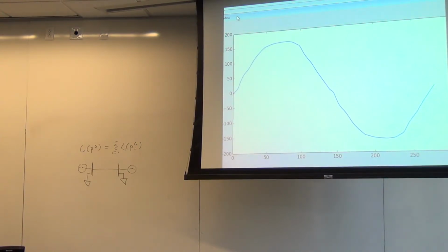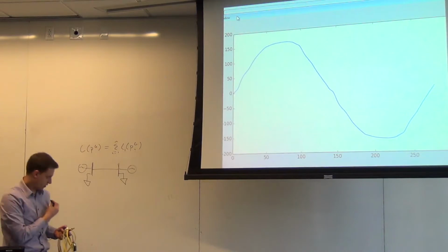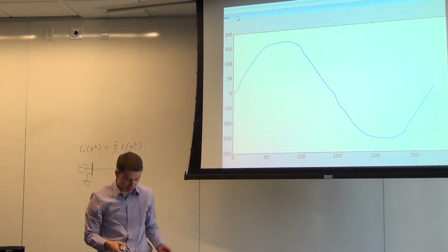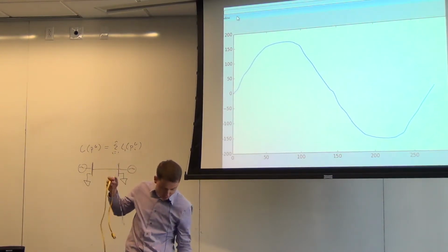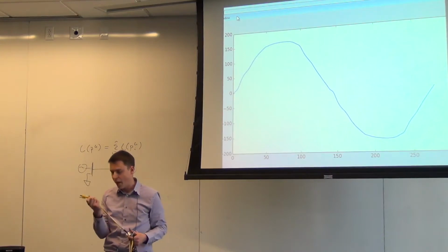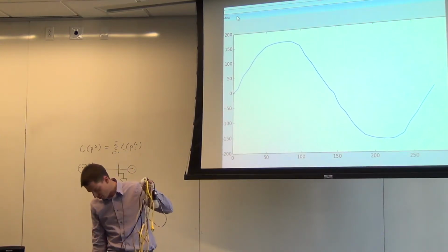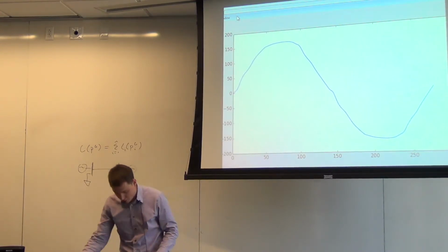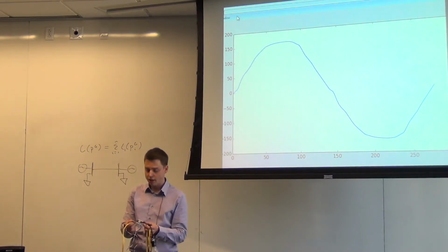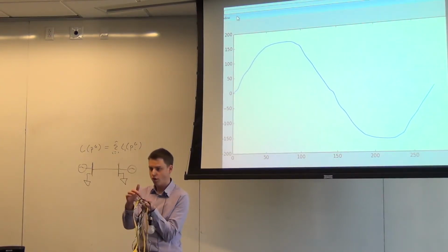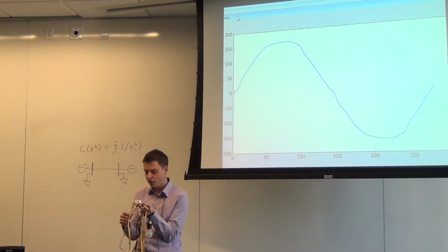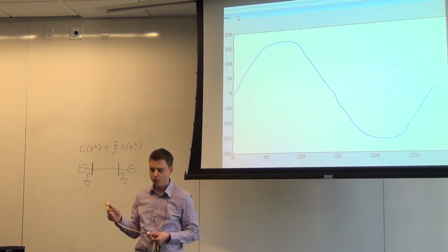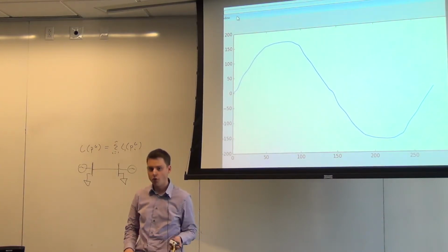Let me actually show and keep in the video what I'm going to do right now. What I'm going to do right now is measure, that's showing voltage. What I'm going to also next measure is current. So what I have here is just a power cable so I can plug loads into the end of the power cable. I got a really long one. This is a power cable where I cut it apart at one point and put a current transformer around one of those wires here. So for whatever's plugged into this power cord, it will monitor the current flowing through this wire.